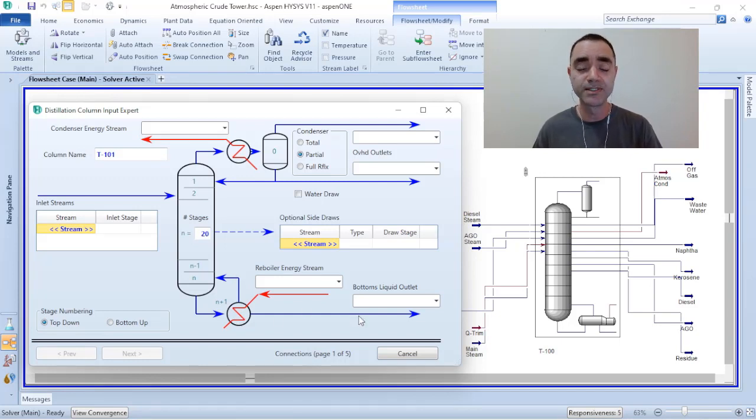So it represents one stage of equilibrium in your distillation column. If you take it into account now, instead of having 20 stages of equilibrium in this distillation column, we have 20 stages of equilibrium plus 1. We have, in fact, a total number of 21. But we need to verify also the condenser. What is happening in the condenser?